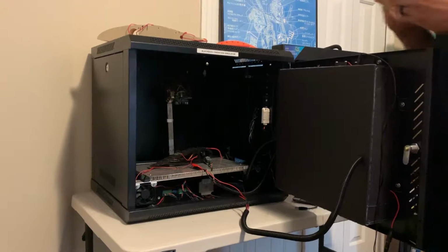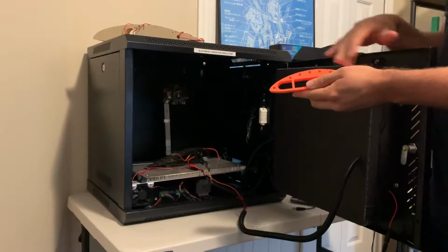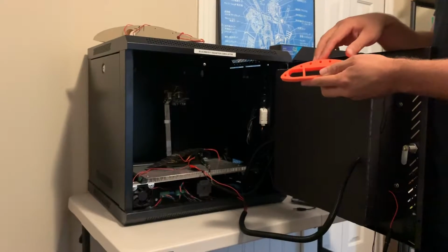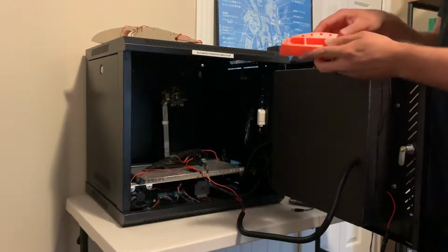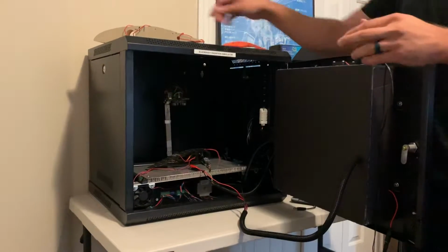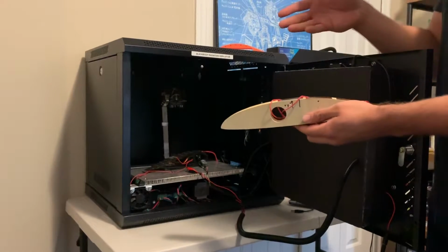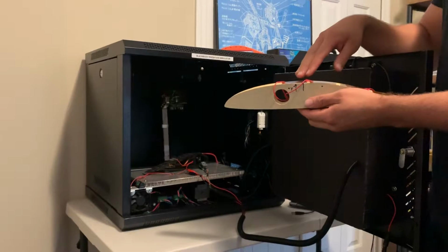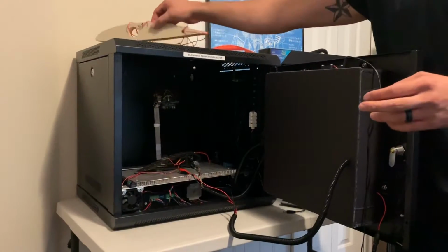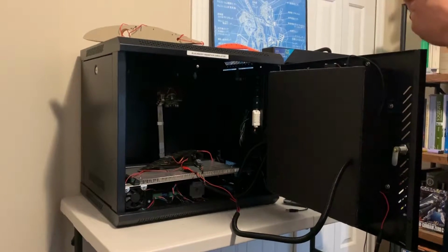What happens is typically I'll have a photovoltaic device embedded onto the surface of an airfoil. This is an LRN 1015, very similar to the MQ4C Triton UAS airfoil. And I just print out a cross section and I can induce a lot of different variables to it. These are an example of the heating elements that I have, because temperature is a very big player in photovoltaic performance. I'm using flexible polyamide PTC heaters, which are controlled through an independent temperature controller, which I'll show on the front end here once I power it all on.